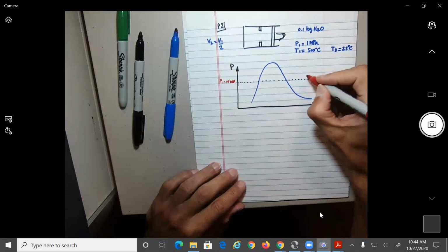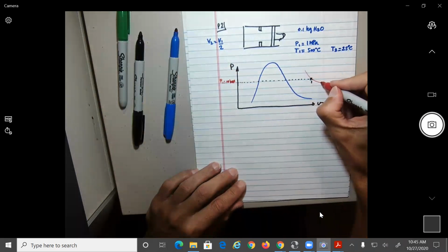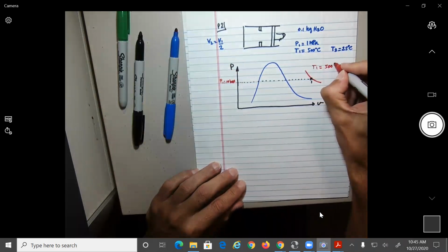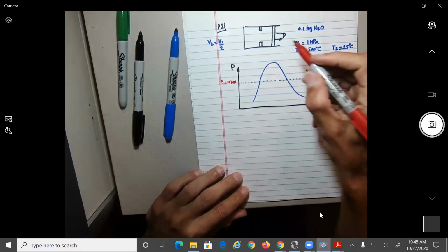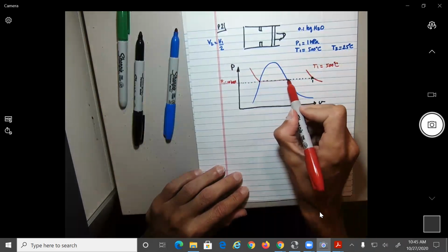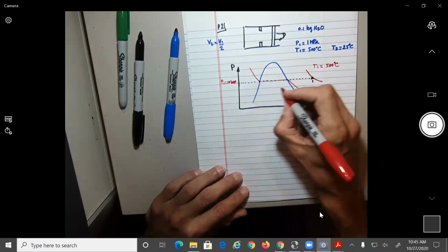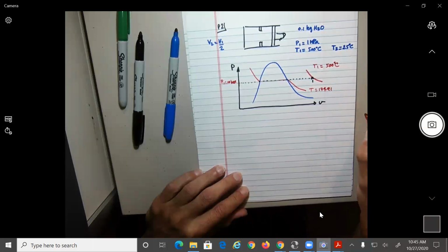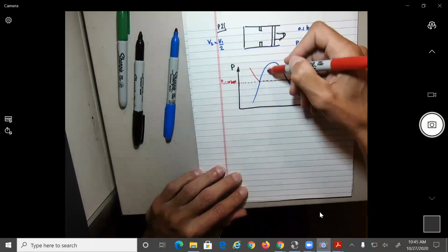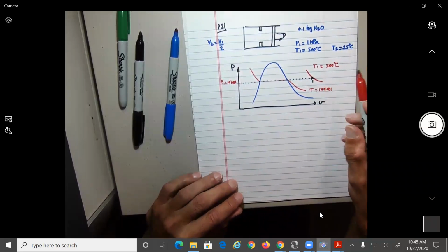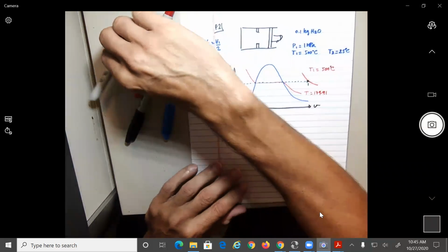This is going to come from one of those temperature lines of 500, because what is the line over here? The line for 10 is 179.91, no? So this should be coming from a much higher pressure, no? But it doesn't matter. The fact is that we know it's superheated. Now, what else do we know?